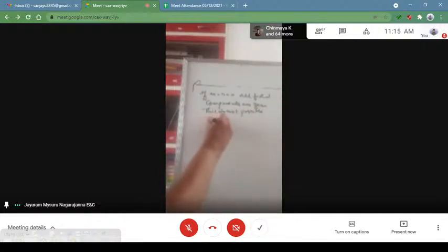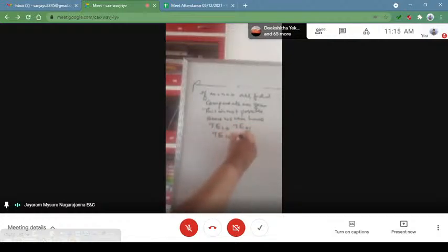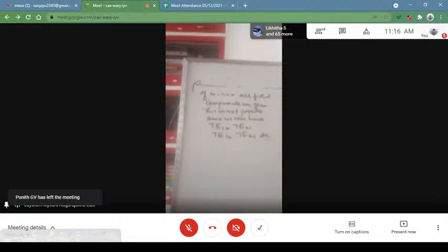Hence, we can have combinations like TE10, TE01, TE12, TE21, etc. m equals 1, n equals 0, m equals 0, n equals 1, and similarly m equals 1, n equals 2, etc. So other than m equals n equals 0, we can have other field components in the waveguide system, and the field pattern can be written in this form.